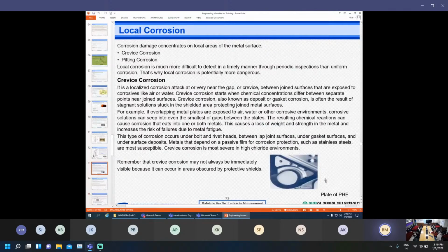We talked about crevice corrosion. Basically it is a plate frame heat exchanger where you can see there are different grooves. If the flow is stuck somewhere in a small groove, that is going to be problematic in terms of crevice corrosion over time. So you must ensure that the path of the fluid flow in the material is good enough to not make a stagnant flow.